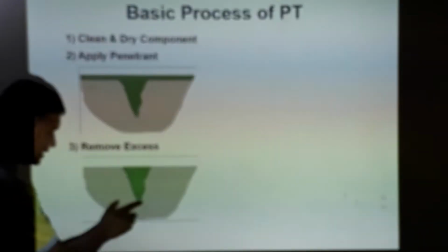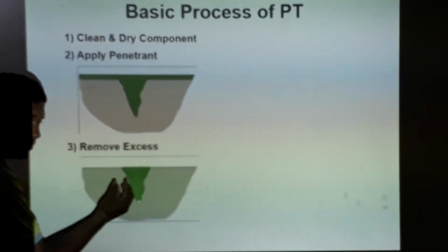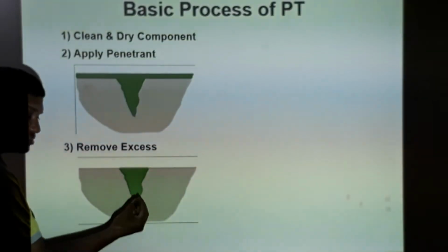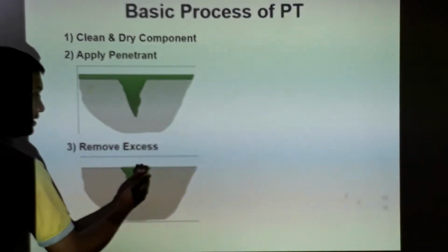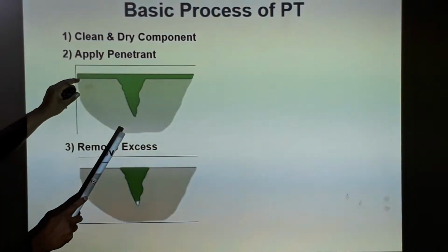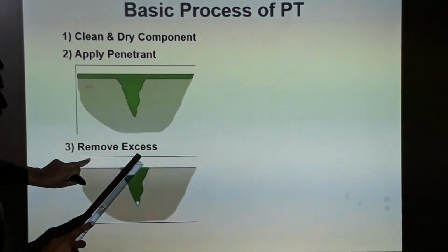This much void will be created at the bottommost part of the defect due to the pressure created by the washing force of the cleaning liquid during the removal of excess penetrant.